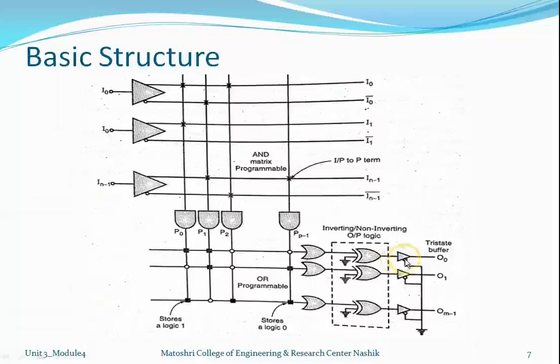Because here, this NOT logic gate again has a switch. If the switch is open, then the output is complemented, and if the switch is closed, then the output is generated in non-complemented form. So in this way, according to the basic structure, the PLA works.